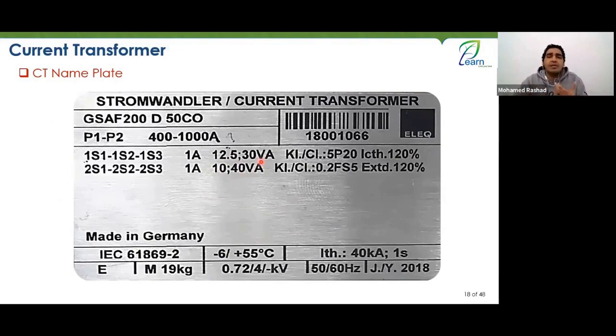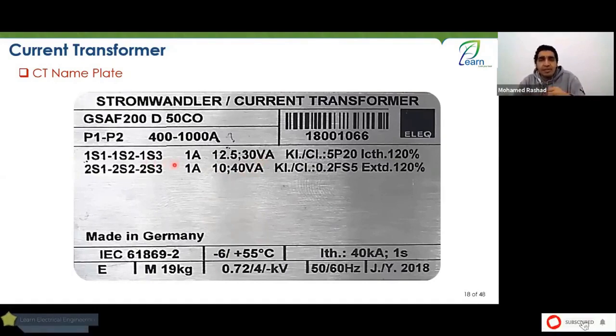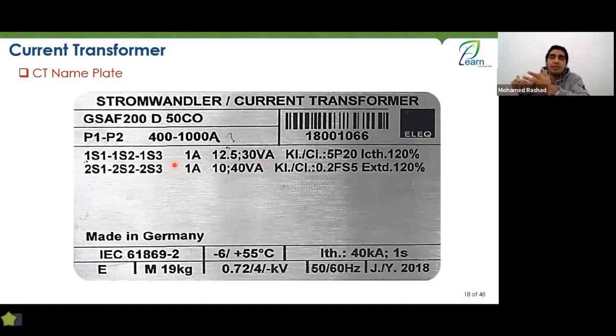Well, does the current transformer provide power? It gives you current, and this current is related to feeding a specific load, and therefore the current in the load is the power. So this power represents the burden connected to the secondary circuit of the current transformer.